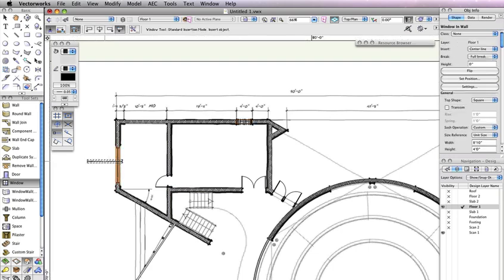For the next window, located above and slightly to the right of the one you just placed, activate the second mode in the toolbar, Offset Insertion Mode. Also, enable the fourth mode in the toolbar, Align Object Left Mode. Now click on the corner to the left of the opening. Move your cursor to the right and click at any point along the wall. Then move your cursor to the right once more so that the preview flips to the right.